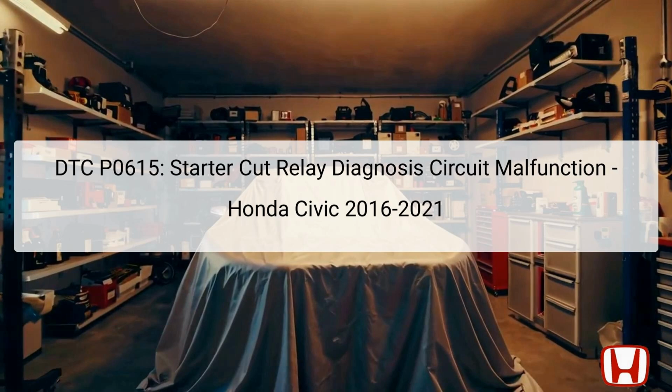The starter cut relay plays a crucial role in preventing the engine from inadvertently starting, which can occur due to various electrical faults. This relay is typically located within the under-dash fuse relay box. When malfunctioning, the circuit may not send the appropriate signal to the powertrain control module, PCM, leading to difficulties in starting the vehicle. In this troubleshooting guide, we will explore the steps necessary to identify and rectify the causes of DTC P0615.